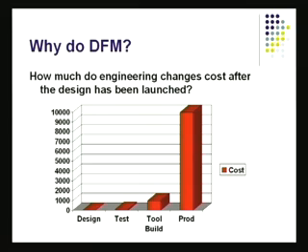Why do DFM? In fact, if you look at DFM, and if you look at the engineering changes that are required many times after the design has been launched, which means after it has been commercialized, if I've not kept DFM in mind, if I've not kept this end step, which is manufacturing, in mind, and if I just do a design and throw it over the wall and it lands up in the manufacturing shop, there are going to be a lot of problems. If you look at engineering changes, many times a lot of things are discovered when you actually get into manufacturing. A lot of problems are discovered when you get into manufacturing. That's something we'd like to avoid, we'd like to minimize.